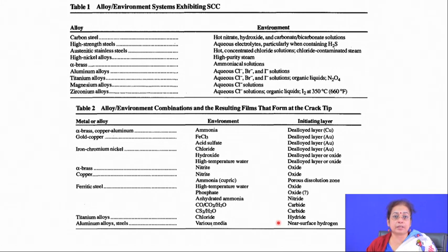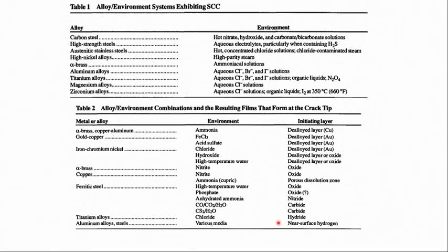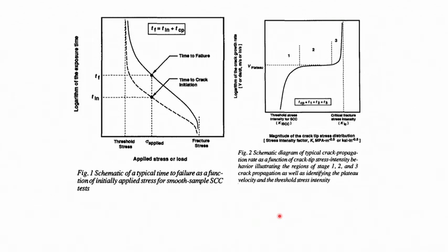You can understand that there are different reasons responsible for stress corrosion cracking. The first is the selective leaching or damage of the typical passive film which protects the surface. The second is that there may be some hydride or other compound formation which is neither protective nor ductile, and is highly brittle in nature. The third may be some other phase formation which is porous, in contrast to the passive film which was needed for protection against corrosion in that environment. So, these are the different reasons for stress corrosion cracking.